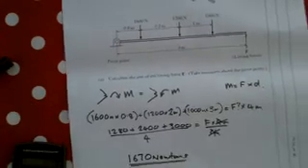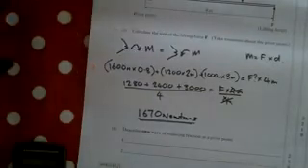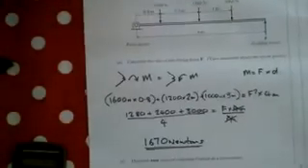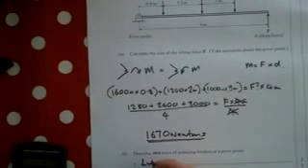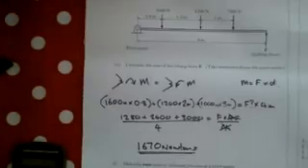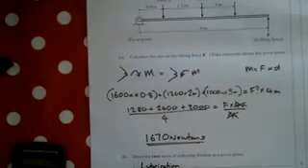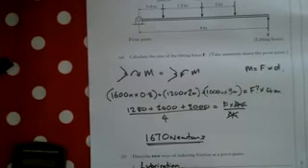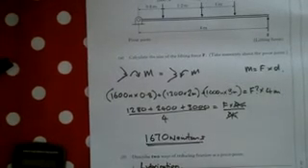Okay, describe two ways of reducing friction at the pivot point. Well, the friction point here needs to be reduced using lubrication. But you could also replace, this looks like a bush bearing, you could replace that with a roller bearing. Okay, over the page.